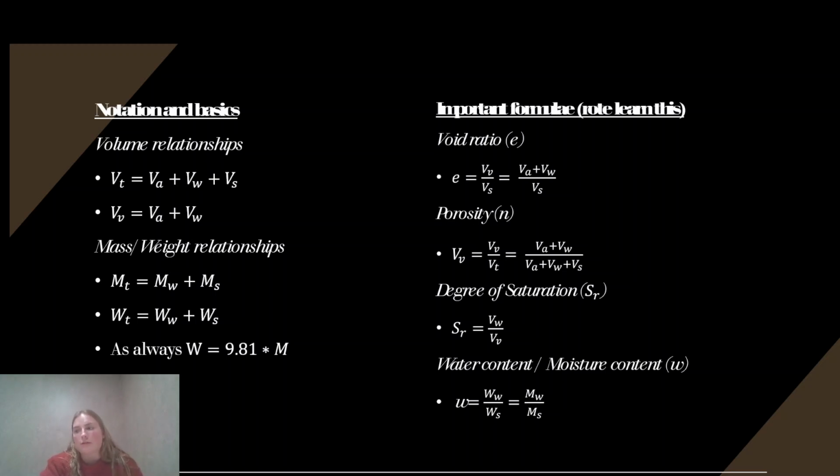And then you can find the moisture content or water content, which is just the weight of the water that's come out over the weight of the dry sample. The reason they set the oven at 105 degrees Celsius is because the boiling point of water is 100 degrees Celsius, so they go just over that in order to make sure all evaporable water can actually be evaporated.